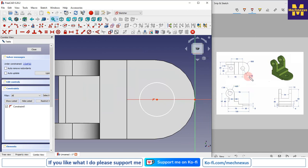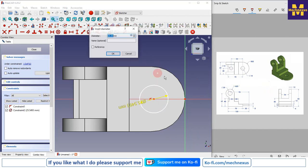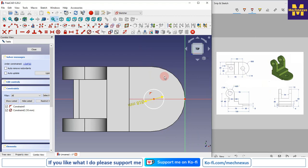This hole position is a diameter 18, so I will select this, give the diameter 18, and its position is R30. So basically it will be concentric with the fillet feature which we have made.